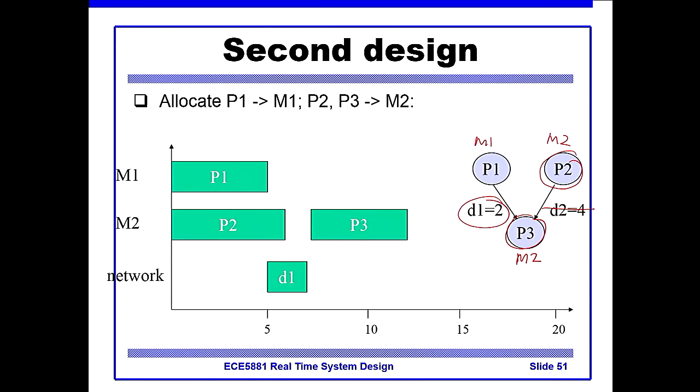But, as you point out, that can overlap with P2. So this is the data coming out of P1, we send it on the bus, and it's going to be loaded into the memory of P2 in parallel with the final bit of processing at P2. And that presumably is done with a DMA transfer because it's not going to occupy the processor of M2. And then there's only a little bit of idle time left, and finally we finish P3 ahead of time. So we can do all that in 12 units of time. And that's done through careful scheduling of time and space.